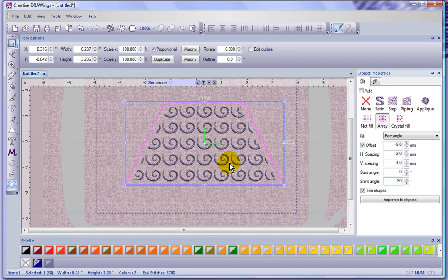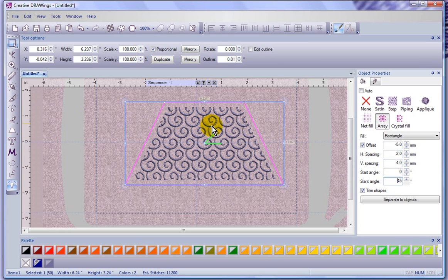Now, if I change the vertical angle, the slant angle, the slant angle is the baseline. What angle is that on? The slant angle is the angle of this green angle, and if I make that, let's say, smaller, so 45, then what it does is it offsets the rows and kind of overlaps the different rows of your little shape.